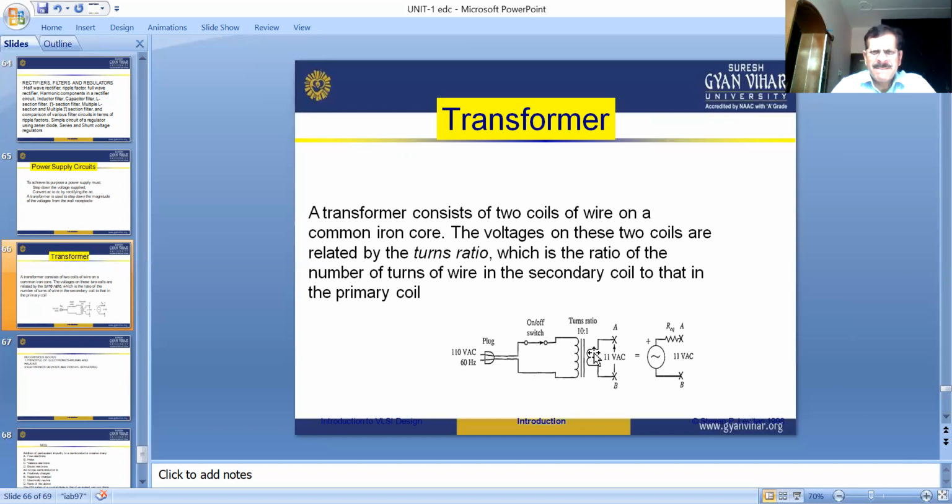And next, after this transformer, we design a rectifier circuit. To design a rectifier circuit, we generally use 4 diodes, in which 2 diodes are in forward bias connections and the remaining 2 diodes are in reverse bias connections. When we apply the input voltage from the supply to the transformer, the transformer steps down this supply and applies it across the diodes.